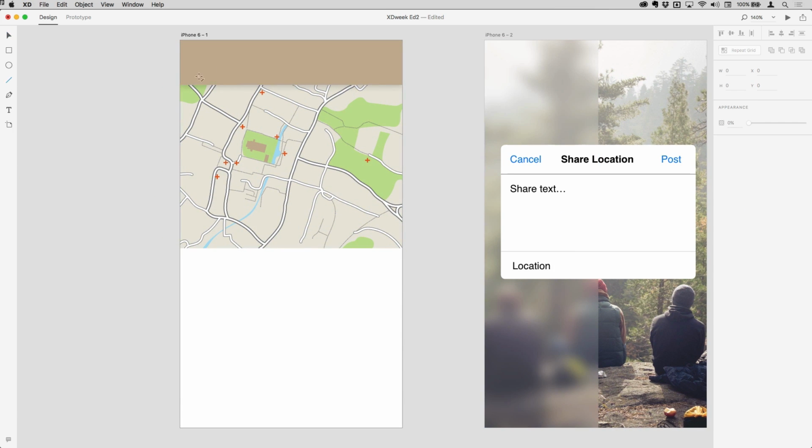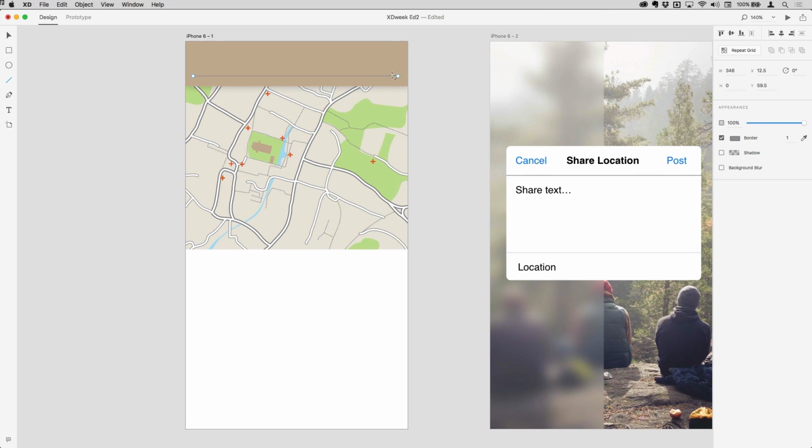There is a line tool just here, and that's simple enough. If you click and drag, then a line is drawn. You can change the dimensions numerically if you want to over on the right hand side in the PI. So for example, if I wanted to set that to be exactly 300, then I could do that and enter that value, and that would be what it is. I can at any point adjust where that is and stretch it and change it, and if I hold down the Shift key you'll see that it's constrained to 45-degree increments there as well. I'll just delete that one.